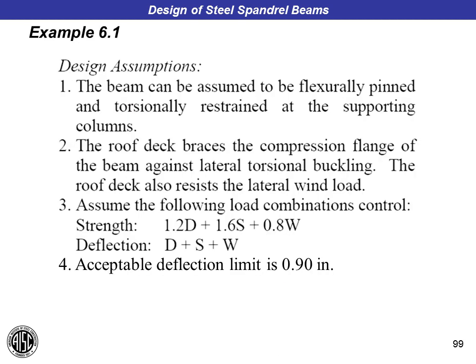So here's the problem statement again. The beams can be flexurally pinned and torsionally restrained at the supporting columns. We have the roof deck to brace the compression flange of the beam against lateral torsional buckling. We're going to assume that we have these load combinations to investigate for strength and deflection, and we're going to limit deflection to 0.9 inches.